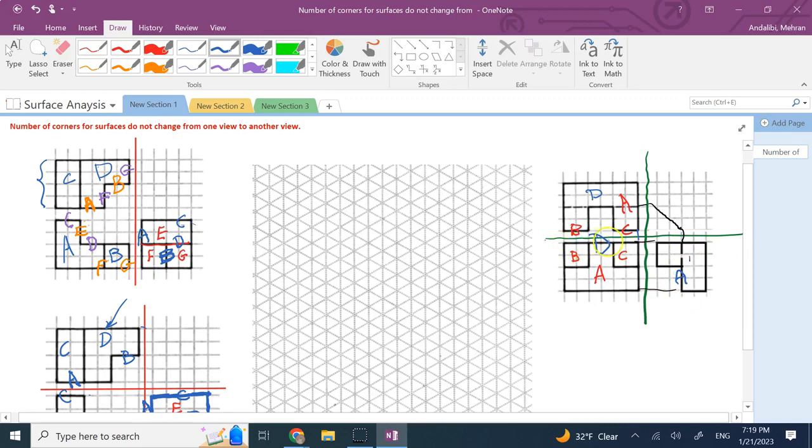What about D? Well, D is on the top edge and it has the entire width of the object. So clearly this top edge here is D because it horizontally matches the front view, and if you transfer the entire depth of that, you clearly see that it has to take the entire depth. So that top edge is D. Let me do a little bit of cleanup so we can continue for the rest of it.